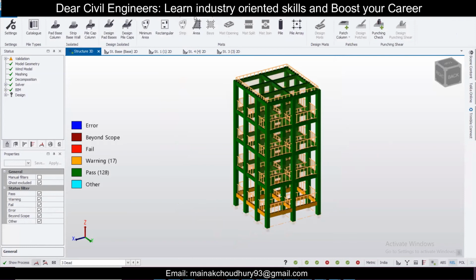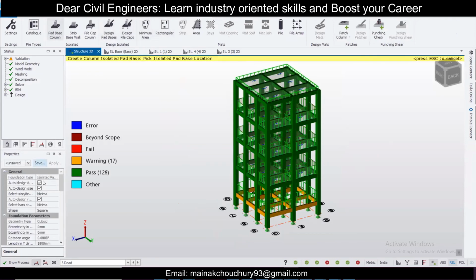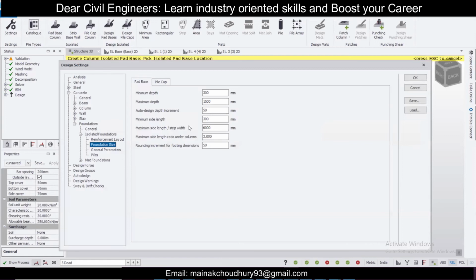If you want to design the foundation here, you can go to your option of foundations, go to pad base columns, and if you want to insert the SBC here, you can find the option of your concrete class and other things as well. And here you'll find the soil parameters. Just insert the soil parameters according to your soil test report, SBC, and soil unit weight if you want to change, and go to the settings.